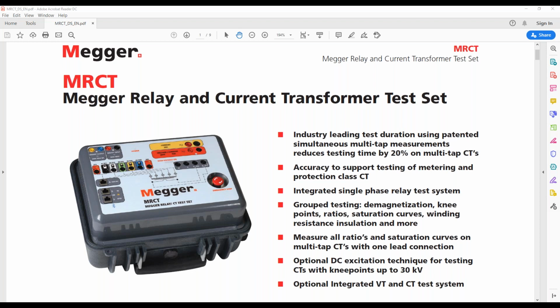The other thing to keep in mind is that a lot of times on the primary side it might be just the center conductor. So to perform this test in a safe manner, the recommendation is to use 500 volt or 1000 volt when performing high to low, high to ground, and low to ground tests.